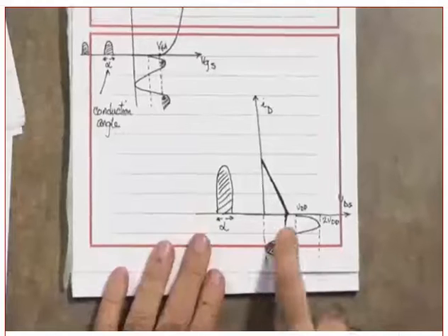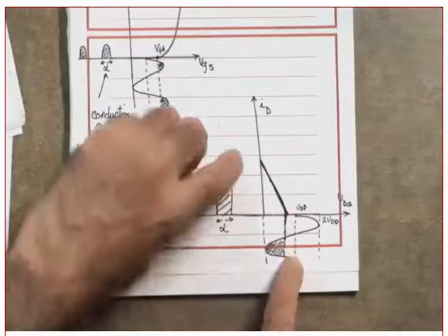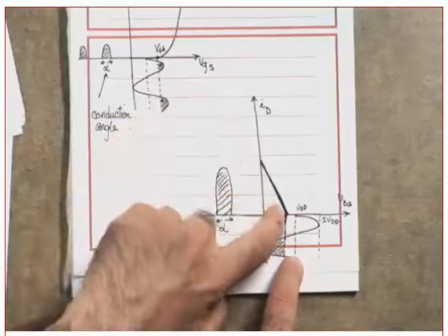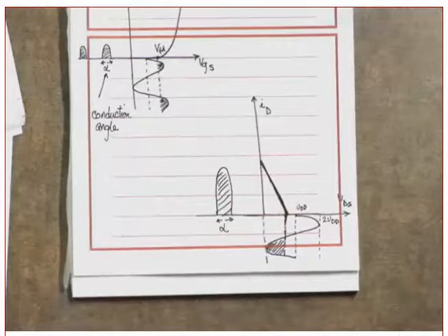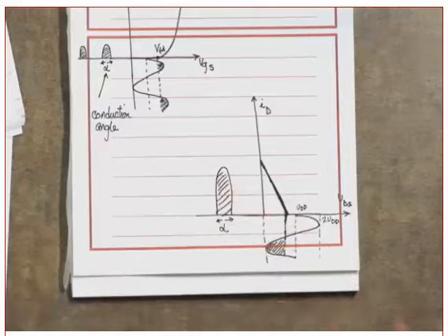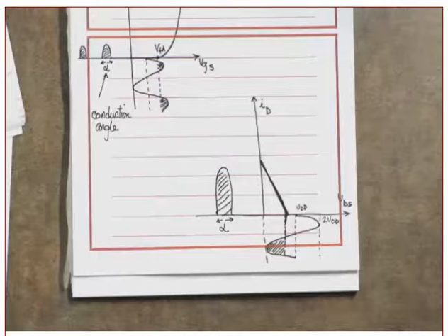Now, show it to me here. Where did I bias? By the way, you see this VDD now? It's still VDD. But now the load line is below it. Which means what? What does that tell you? The IDQ. What is the IDQ? IDQ is the quiescent current. Now what is it? Is it negative? It's negative. Remember in class B, what was IDQ? 0. Now I'm going even lower. So the IDQ, the quiescent current, is negative. Did you get this or not?